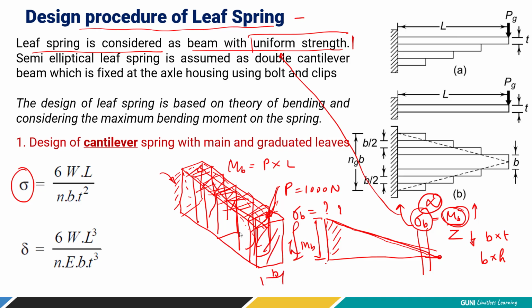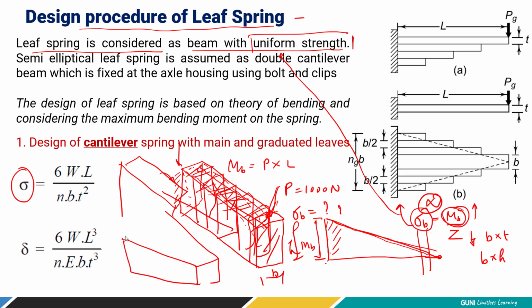So what we have to do is increase the width, right? Let me look at it from the top. Instead of making a beam of constant rectangular cross section, we have to make a tapered beam like this. Just try to see, right? At the fixed end, it is going to be a heavy section width-wise, but as you move away, the width gradually decreases, right?